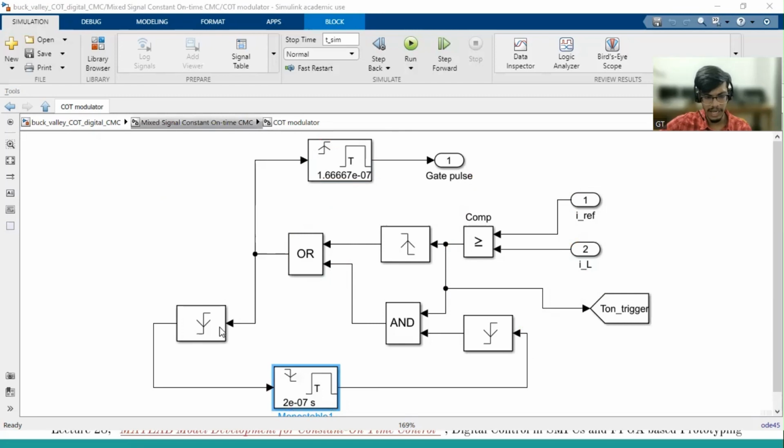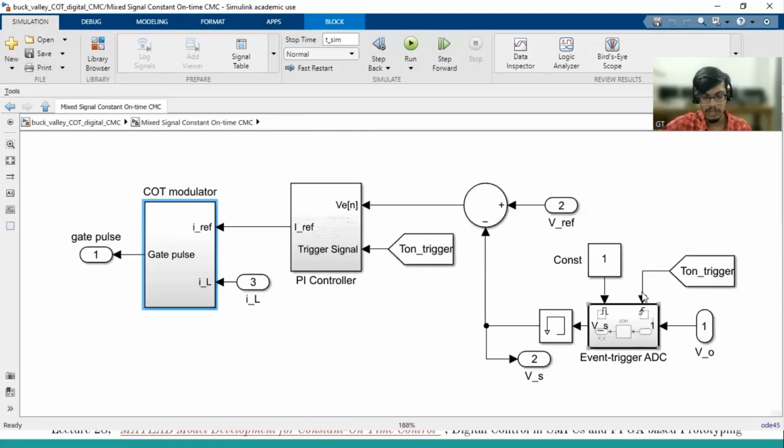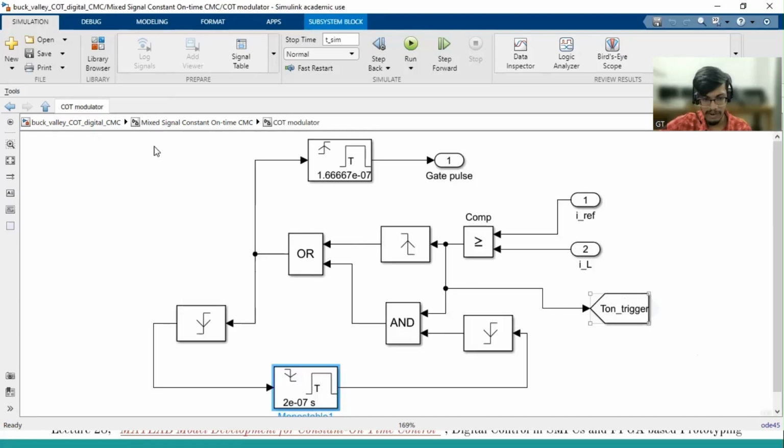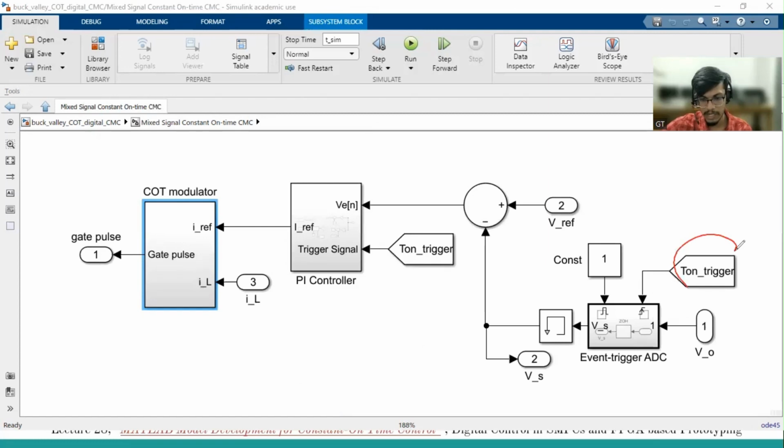So this is exactly the same as analog. There is nothing new. Only the orientation differs; maybe the block SAR is using another sub module, but here everything is open. So the only difference, as I have shown, is this event. I use that event to sample two things. One is this V0. That event is used for the V0 sampling, as well as the controller computing the reference voltage based on this event.